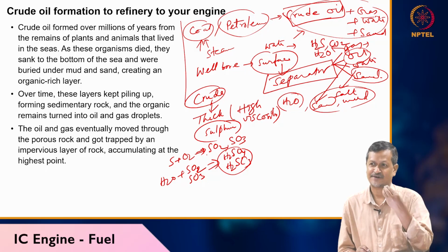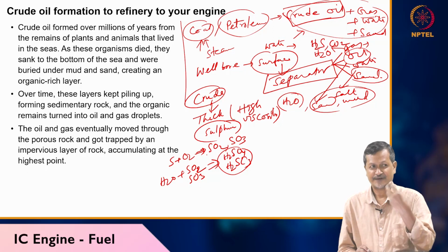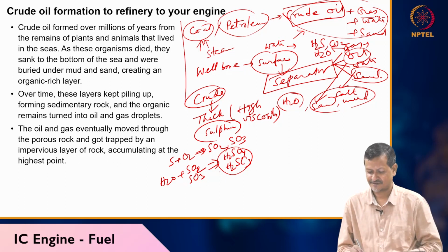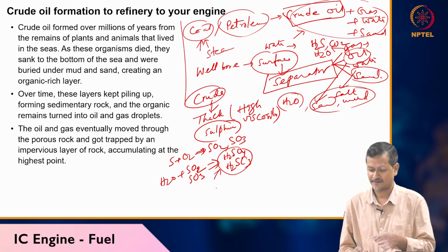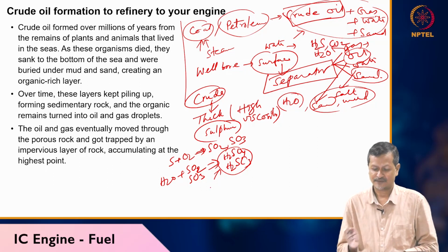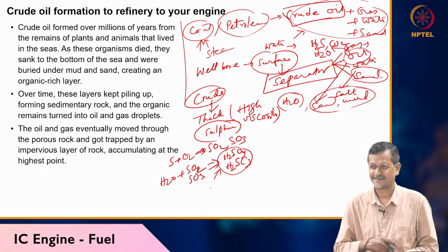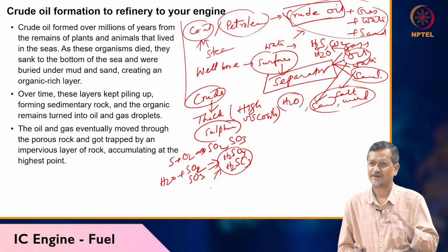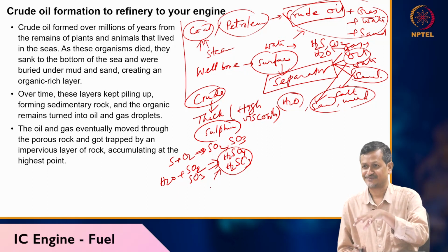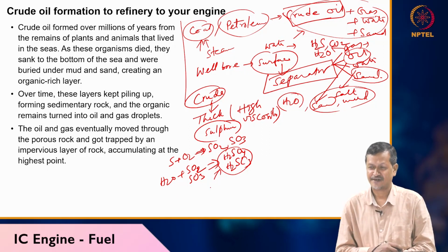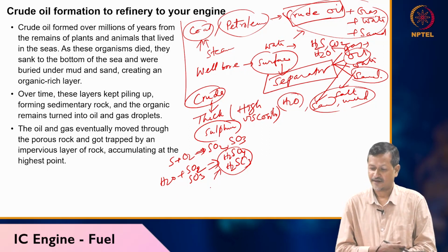If you are smelling hydrogen sulfide, H2S, directly, you can die, okay. If you have acid also, it's very much dangerous. If concentrated sulfuric acid or sulfurous acid is there, that is also very much dangerous. Another way it is dangerous, it will be corroding all the metal parts, okay. So it is harmful for the environment, harmful for your machinery also. So if you have any sulfur content, you have to remove it.